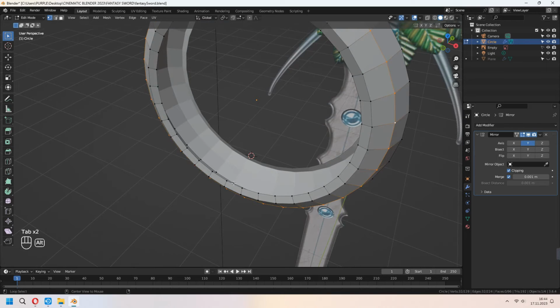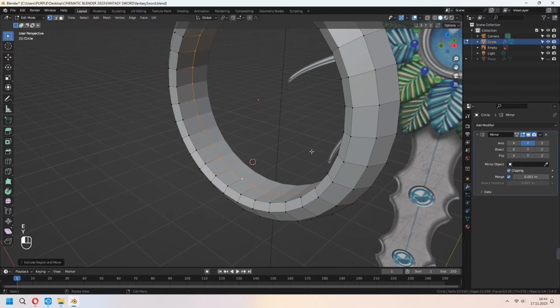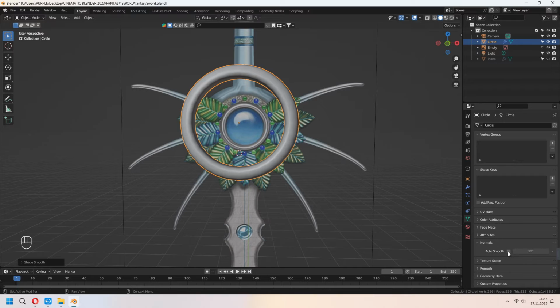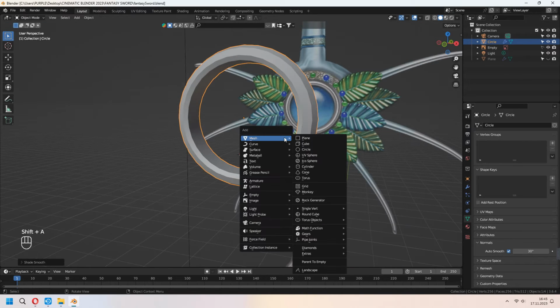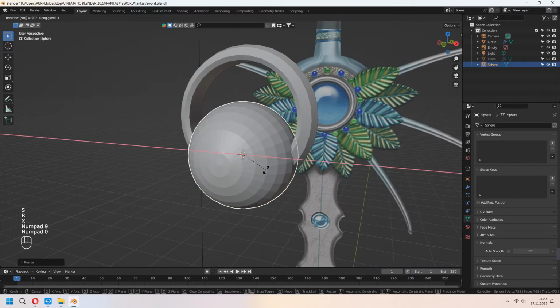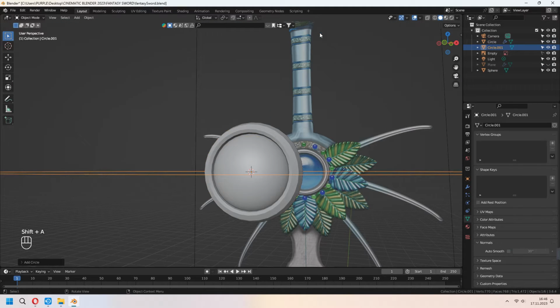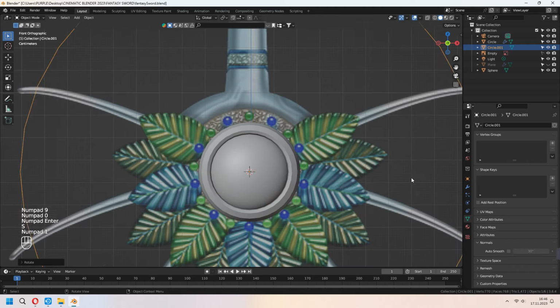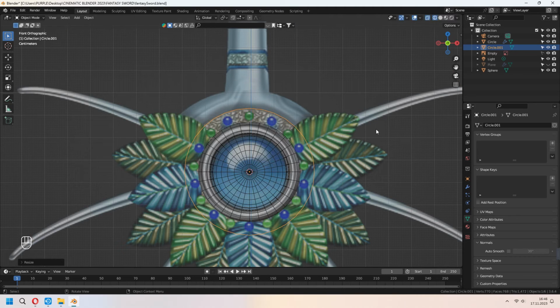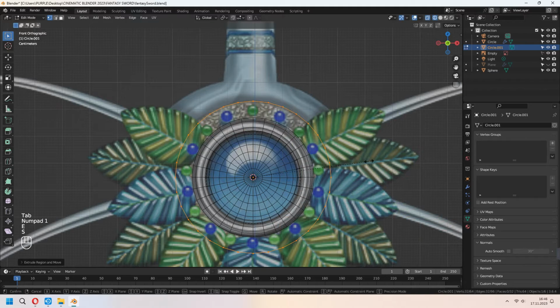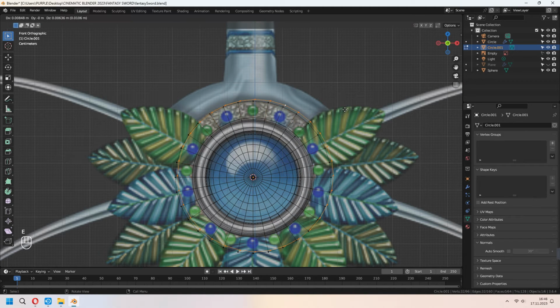And choose the inner part of it with Alt and press E to extrude your vertices on the Y-axis. Shade smooth and auto smooth. For the middle part of it, the glossy ball, I will add a bit of a glossy look. You can add a UV sphere. For the outer part of it, you can add a circle again. And you can press E to extrude and S to scale. Again, do the same thing, E to extrude, right click and S to scale.